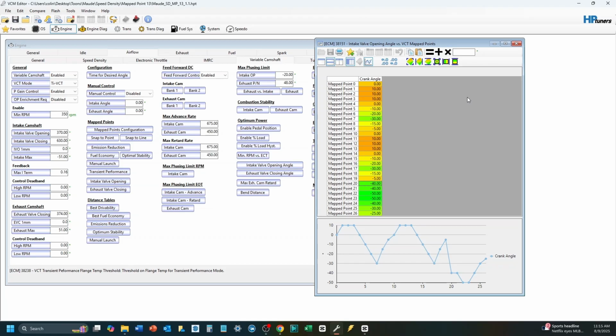So why are we doing this? So again, the whole reason this started is this is the most fundamental fuel trim operation you need to perform. It's step one in an order of operations. And it's peculiar because normally you would go MAF, then speed density, right? Then worry about torque, fuel blending, spark, right? For this, it's not quite like an F-150 where we just do speed density and that's it, right?